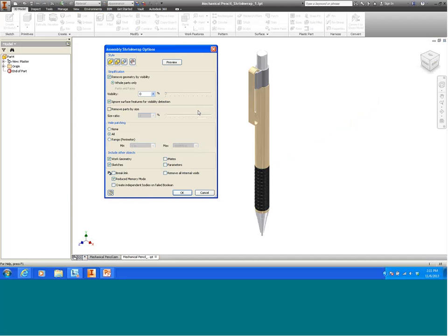The part file is created, yet it doesn't know what geometry I'm going to include or show in my shrink wrap. So I get this dialog box that comes up next. I mentioned you start at the top of the dialog box. This is the style, which defines what the final geometry is going to look like. Of the options on the left-hand side, there are 2 of them that represent solid bodies, being a single solid body.